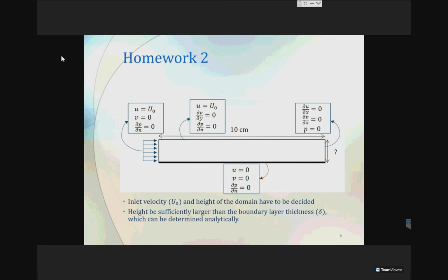But when you specify this problem in OpenFOAM, do you remember you also have to specify the third direction? You have to specify the z direction as well. But the z direction is easy. You just specify a hypothetical length in the z direction and then choose the empty boundary condition. We will see that. So the z direction is specified in OpenFOAM, but that's empty. It is basically a 2D problem.